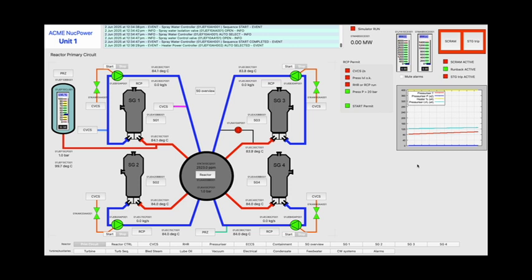As the primary coolant temperature rises past 100 degrees, the pressure will also start to rise and follow the saturation curve, at least for the water near the heaters within the pressurizer. Primary coolant in the rest of the system will lag a number of degrees behind the saturation curve. This process is rather slow, but in real life it is slower still. We can skip forward as this may take some time.